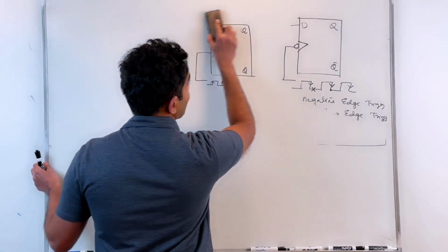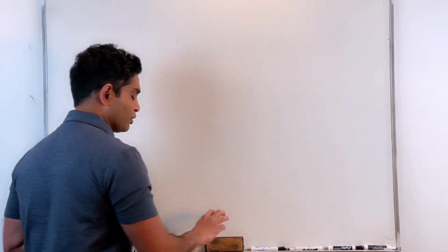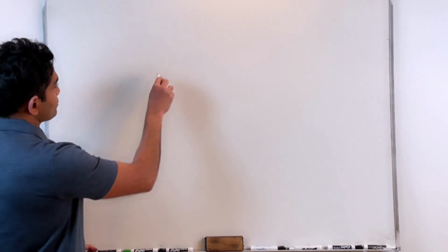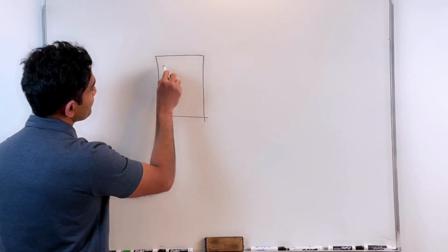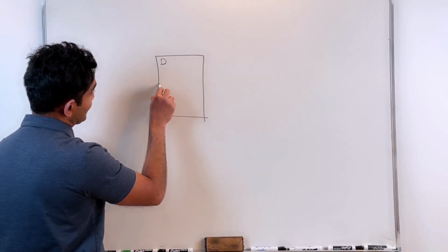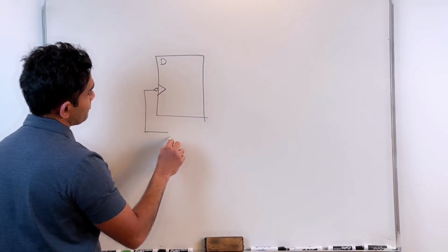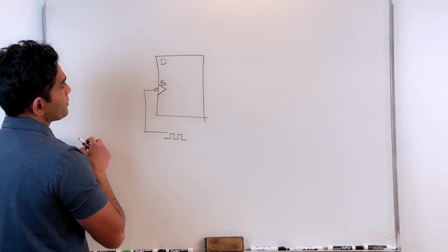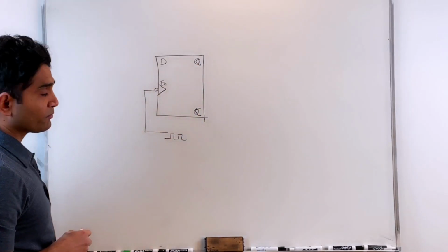I just modify that a little bit with some combinational logic, and I obtain this, and see what purpose it serves. So I take a single D flip-flop. This is an edge triggered flip-flop. Let's say this is a negative edge triggered flip-flop. That's where you apply the clock. That's your Q and Q prime, two outputs available to you for use.